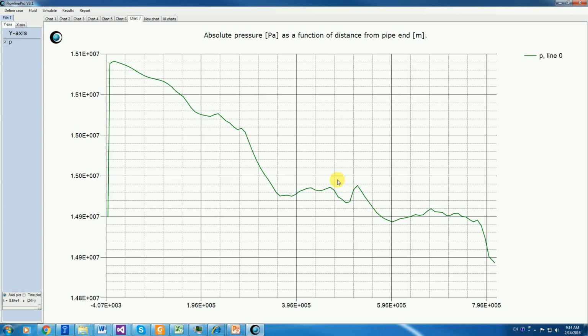Losing the heat after we have closed the outlet end takes much more than a day, while spreading the gas in there so that there's almost no pressure loss goes very much faster. So the insulation of the pipeline, we can then conclude, is the main parameter. The thermo-insulation is the main parameter in deciding how fast it responds and how fast it stabilizes to changes.